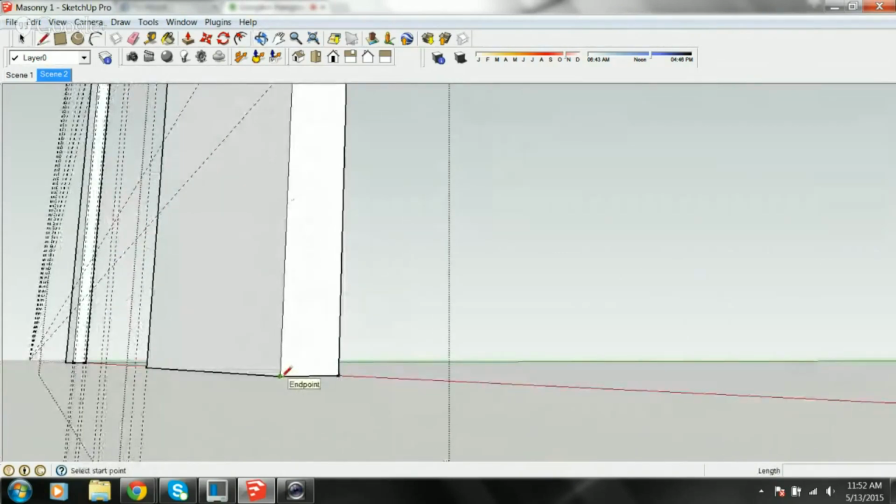Okay, in the architectural world, a standard size brick is 3 bricks is 8 inches tall. Okay, so 9 bricks is 24 inches. Well, I'm not going to get that detailed in this particular model for this current video. I just want to show how we can put the mortar lines in. So that's like 2 3/8 or 5/16 inch tall with a 3/8, 5/16 joint. But we're going to make it simple.